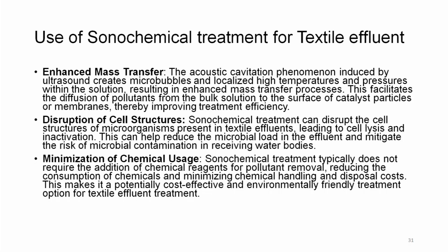Enhanced mass transfer. The acoustic cavitation phenomenon induced by the ultrasound creates microbubbles and localized high temperatures and pressures within the solution, resulting in enhanced mass transfer processes. This facilitates the diffusion of the pollutants from the bulk solution to the surface of the catalyst particles or membranes, thereby improving the treatment efficiency.